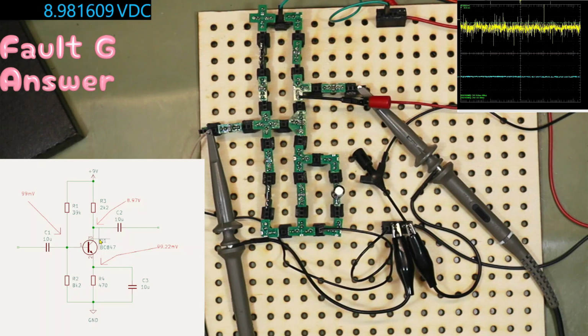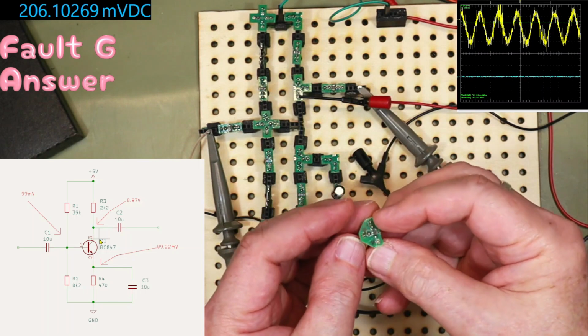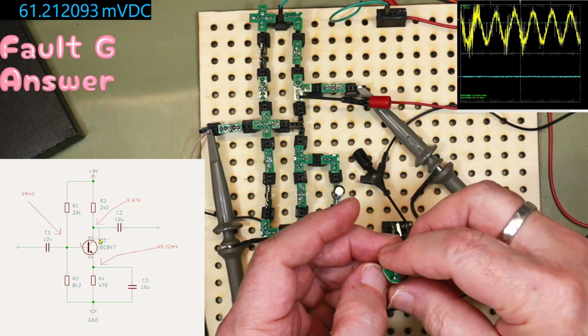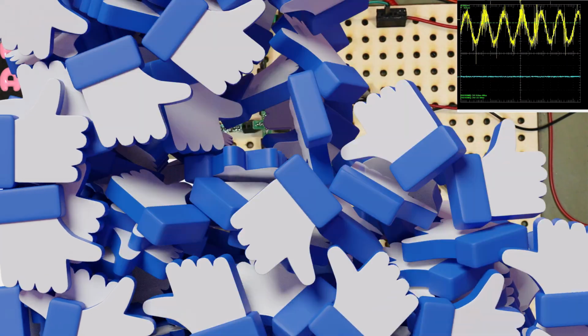And so what would you guess would be that fault? Well, let's turn power off and we'll pull this out and we'll have a look. And what have we got? We have a short between the base and the emitter. Again, if I pull that out and put it back in, the circuit would work fine.